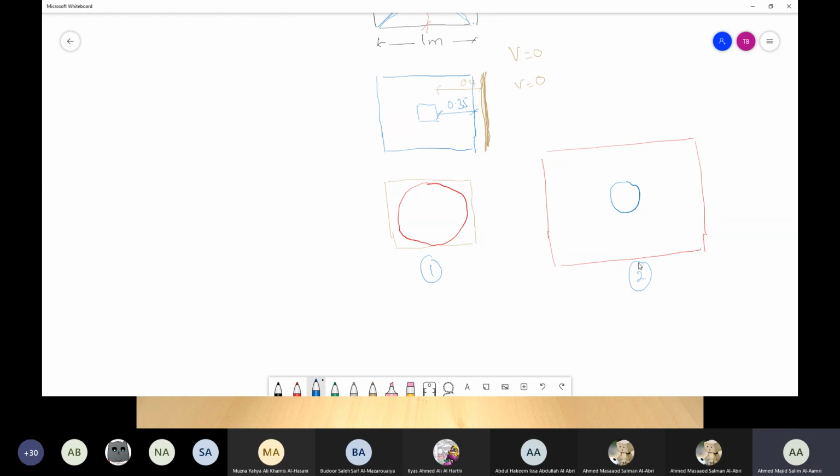So that's why, if your shear line of one-way shear or two-way shear is happening beyond the foundation, it means that there is no shear force. I don't require anything to lift the portion which is outside the foundation. There is nothing existing after the foundation. That's the scenario that you should know, maybe for your mid examination.